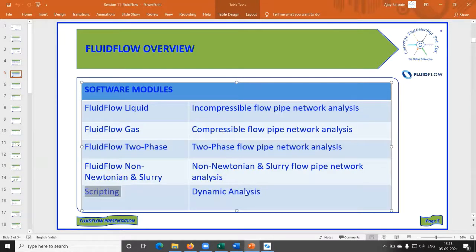Sir, I think hydraulic simulators are limited to the calculations associated with piping networks or fluid flow, two-phase or multi-phase. But process simulators have no limit. They can simulate any unit operation and unit process. Correct. So if I want to do distillation column sizing, I cannot use a hydraulic simulator. That is only for pressure drop calculation, right?